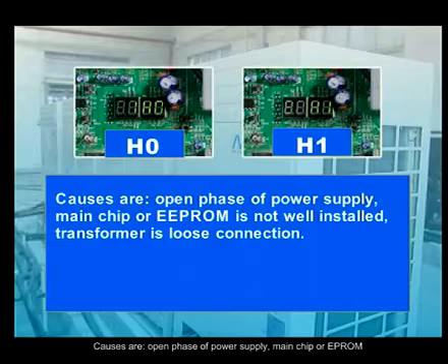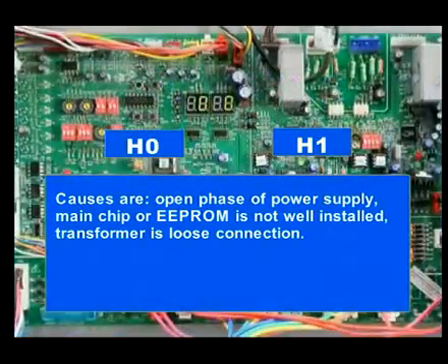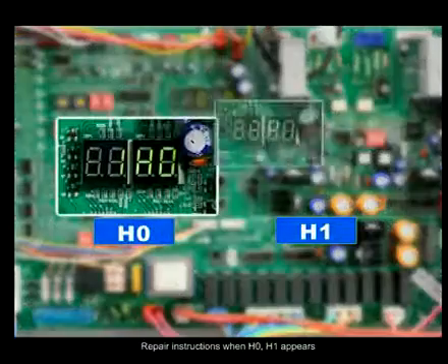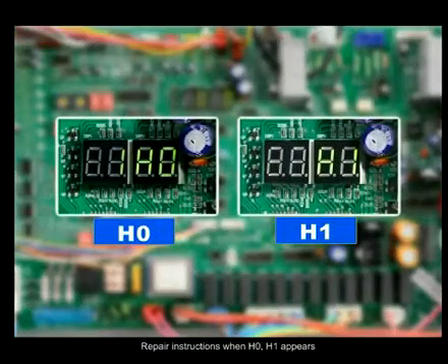Causes are open phase of power supply, main chip or EPROM not well installed, or transformer with a loose connection. Repair instructions when H0, H1 appears.